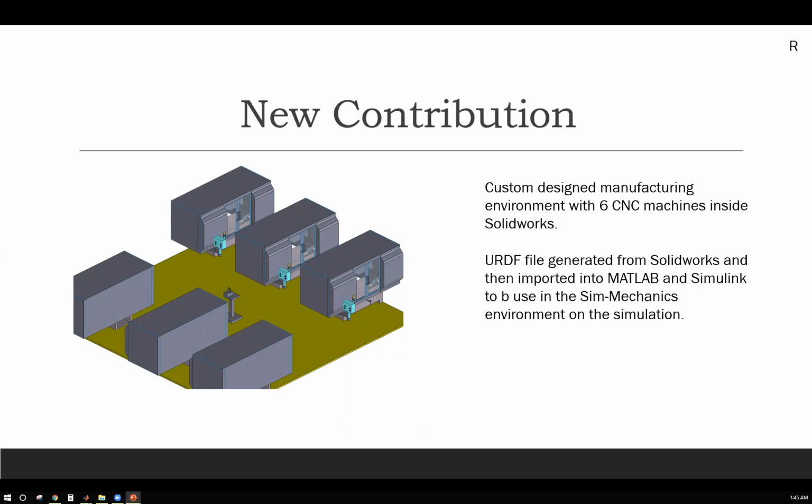However, that was not working very well, and the environment would not transfer properly into VRealm. So we decided to use the SolidWorks to URDF exporter and transfer the environment as if it was a robot with fixed joints, and that transferred very well. Then we meshed that with SimMechanics, which Alfredo is going to be discussing later. Next slide, please.